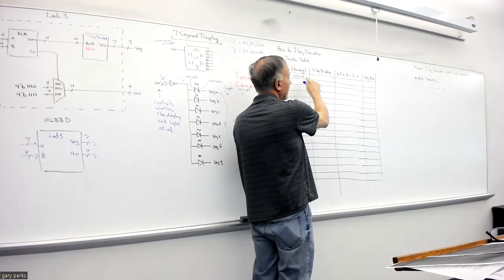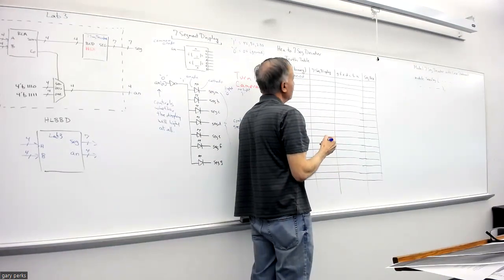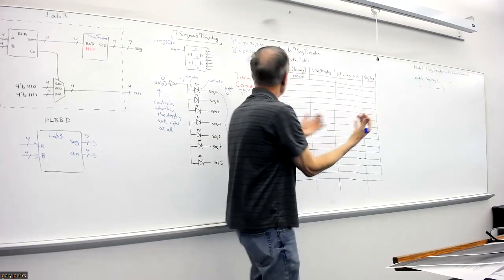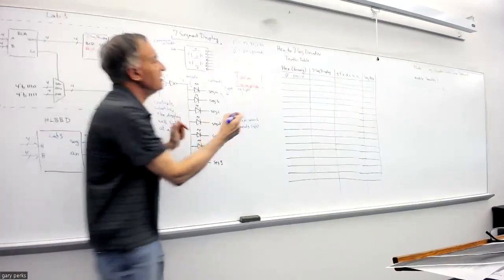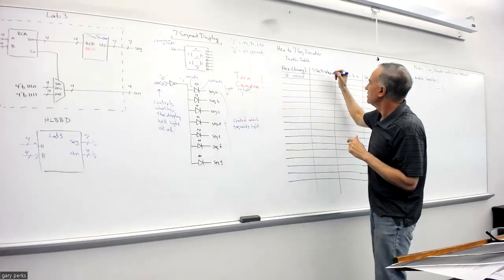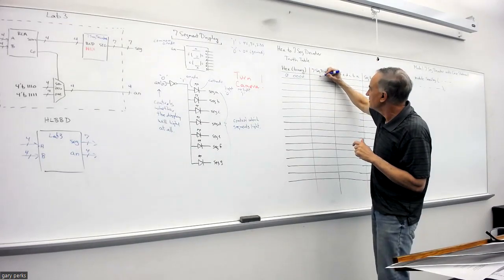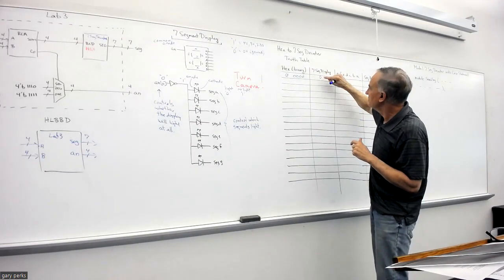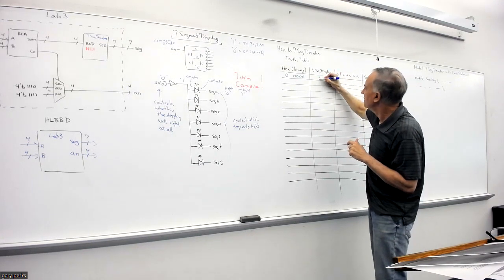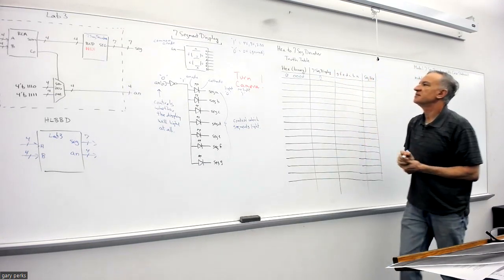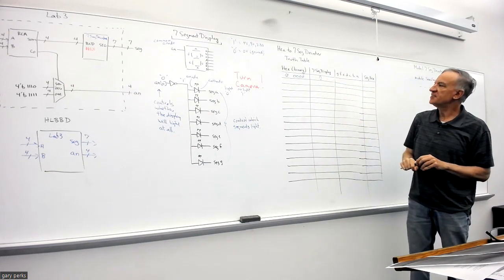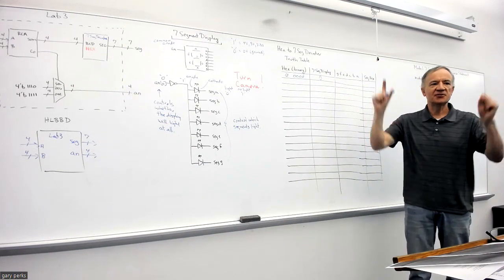If we have a 0 coming into that decoder, what we want to see on the 7-segment display is all the segments lit except for the middle segment. So when we have a 0, we want all the segments to light except the middle one, because that would show us a 0.